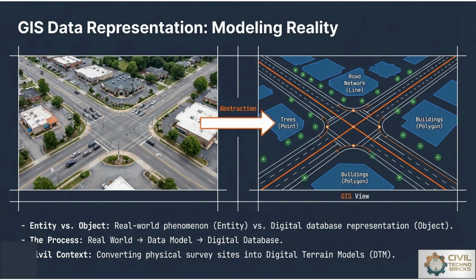So, GIS data is broadly classified into spatial and non-spatial data, which is used to represent real-world features. The objective behind that is to accurately model the geographic features for analysis and decision-making processes. The data is stored as grid cells, which we call raster, or in terms of points, lines, and polygons, like vectors. So raster and vector are the two working principles of data representation in GIS.